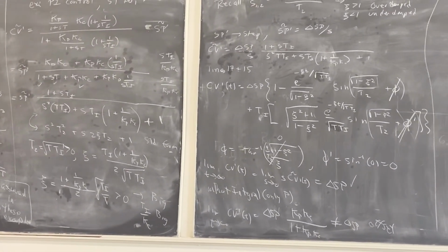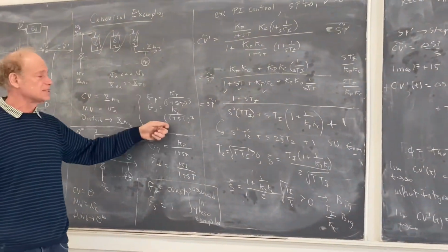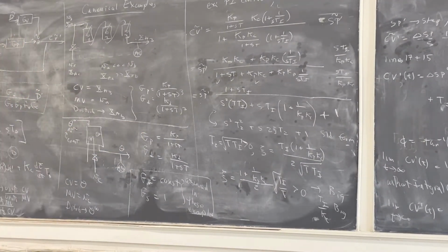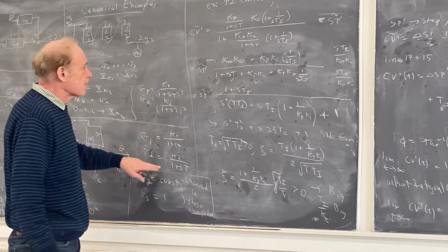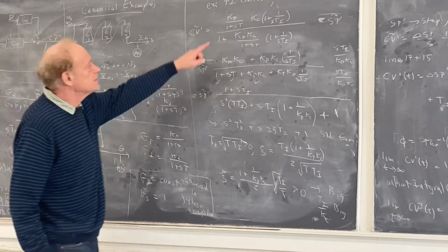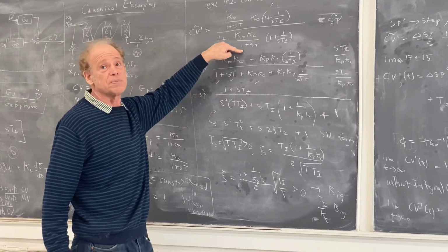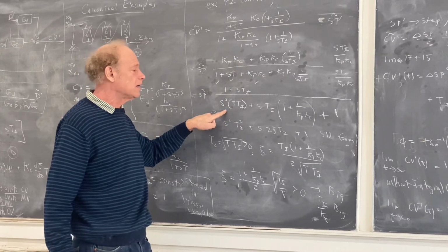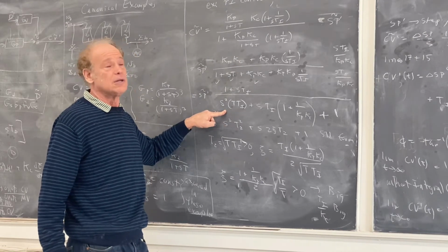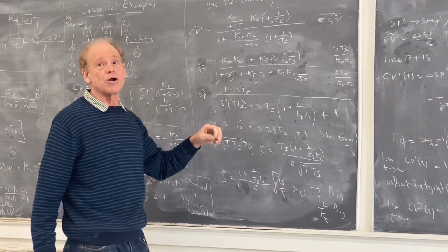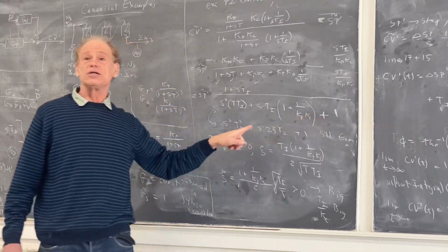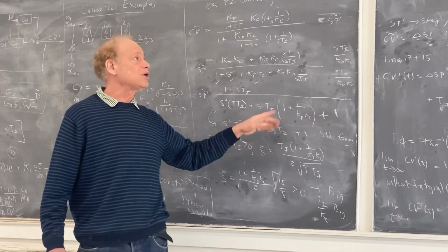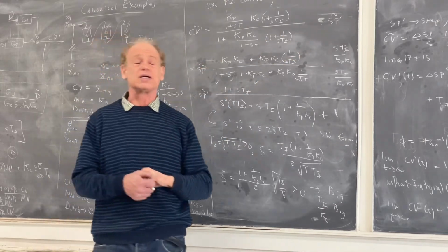But once you get to more complicated systems, like second or third order processes, we saw that you could lose stability very easily. You could imagine that if I were doing this canonical example, but instead of 1 plus st, these were 1 plus st cubed, then when I multiply out, instead of getting a quadratic, I would have gotten a quartic equation. In a quartic equation, when I start playing with the coefficients, all hell could break loose and I could lose stability. The quadratic is pretty simple, but once I get to a quartic, it's not that simple.